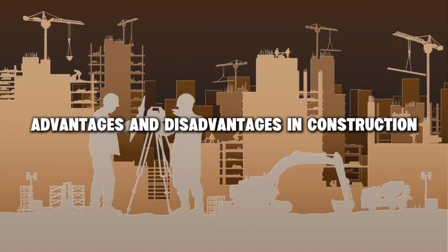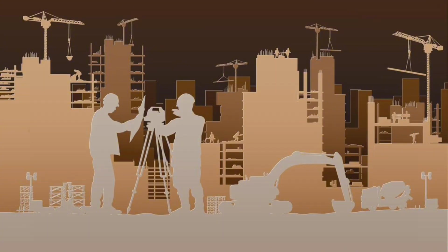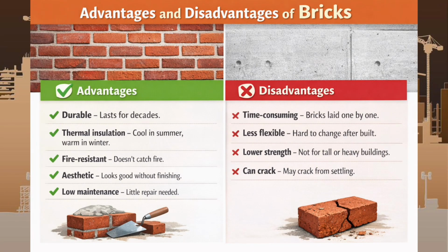These are the advantages and disadvantages of using brick as a building material. First, let's review the advantages. First, they are durable and last for decades. Second, they offer thermal insulation, keeping structures cool in summer and warm in winter. Third, bricks are fire resistant as they don't catch fire easily. Fourth, they are aesthetic and look good without needing extra finishing. Lastly, they require low maintenance.